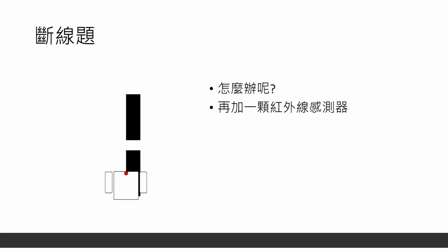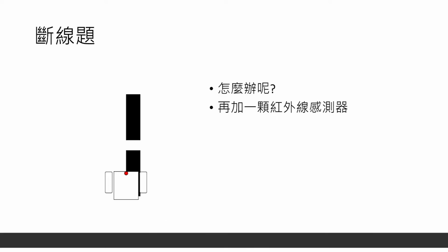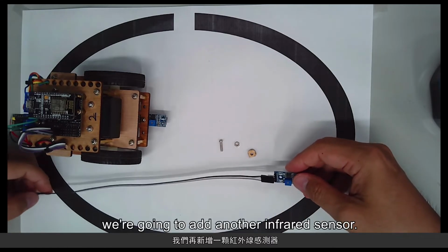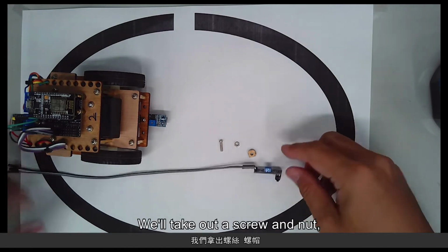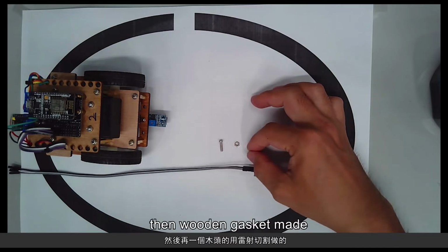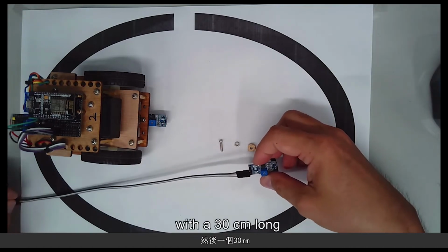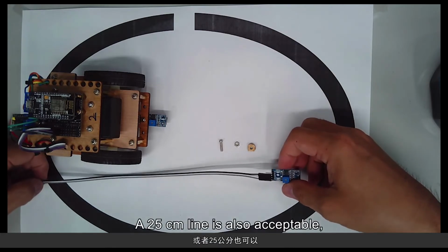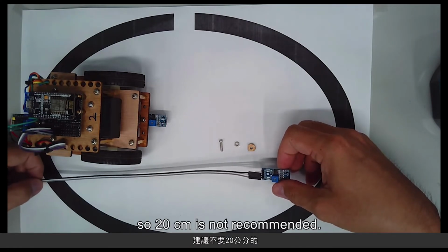Why can we have an assistant for evaluation by adding a second sensor? Let's take a look at how we're going to add another infrared sensor. This one will be used as an assistant for evaluation. We'll take out a screw and nut. We'll use a 12 mm screw, then a wooden gasket made by laser cutting, as well as an infrared sensor with a 30 cm long DuPont line. A 25 cm line is also acceptable, but a 20 cm one is too short, and sometimes it would be hard to connect the wires, so 20 cm is not recommended.